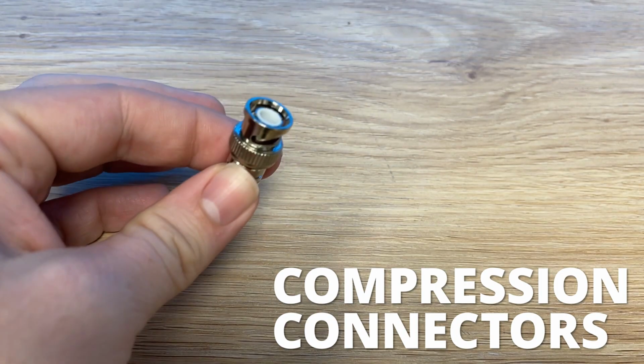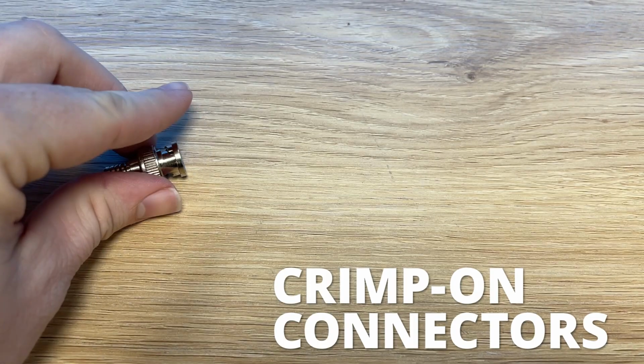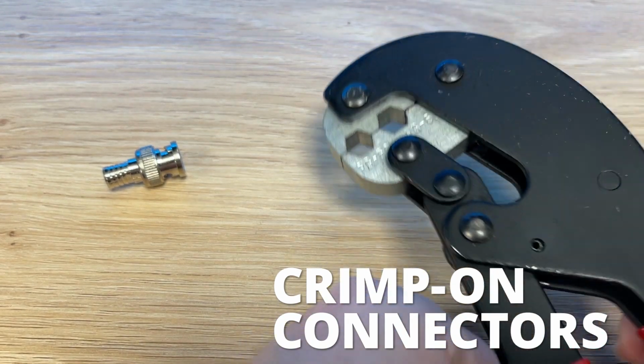And second, if you are buying your cables in bulk and putting the connectors on yourself, just be sure to have really nice and tight connections on both ends of the cable. For most scenarios, we recommend going with compression connectors. Compression gives you a much more even and much more reliable connection, whereas opting for a crimp-on style of connector sometimes can give you an uneven connection. It can crush your cable into unnatural shapes, and just leave you with some less than ideal connections. So that's cable construction. The second mistake I made with this installation was the actual method that I used.